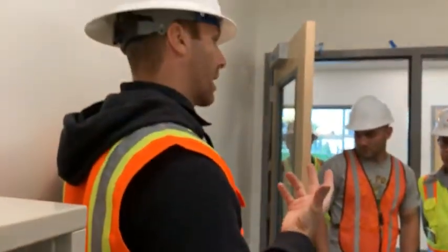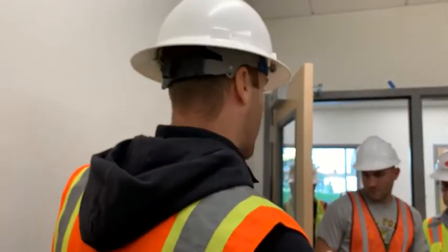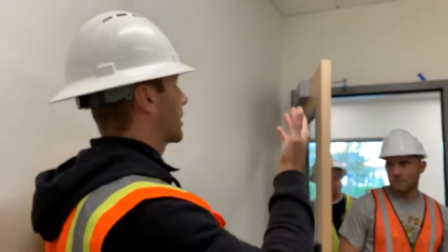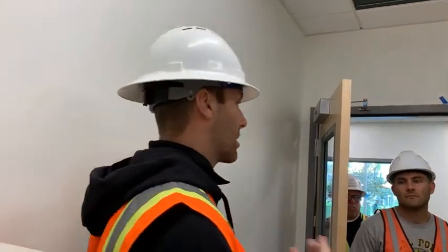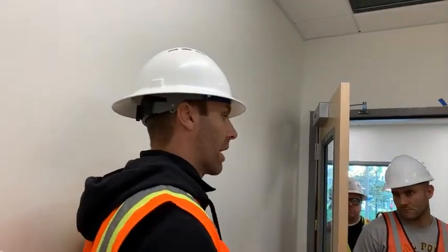So in here, even though we wouldn't have a lighting relay, we do have a receptacle relay. That relay is blue. So coming out of that switch, most likely hit the receptacle relay. It's probably up on the wall somewhere here, and then fixture, okay? And that would be if it was like a standalone room, that's all you have.